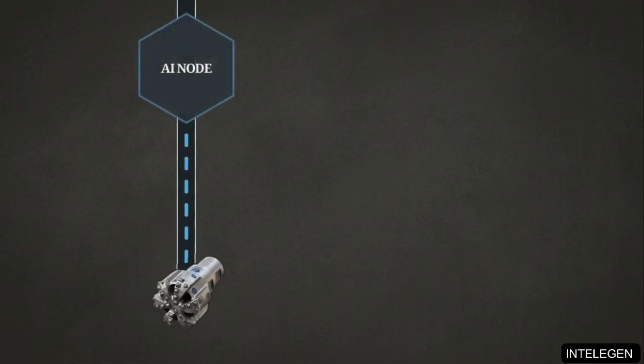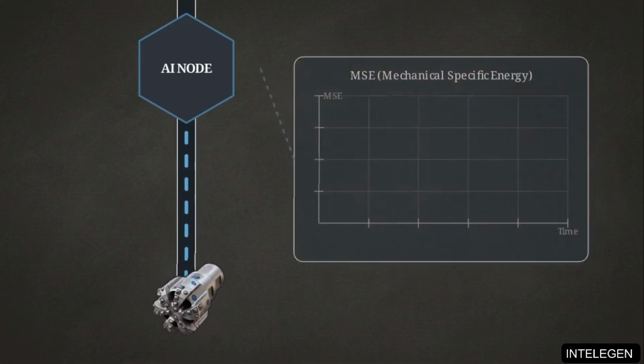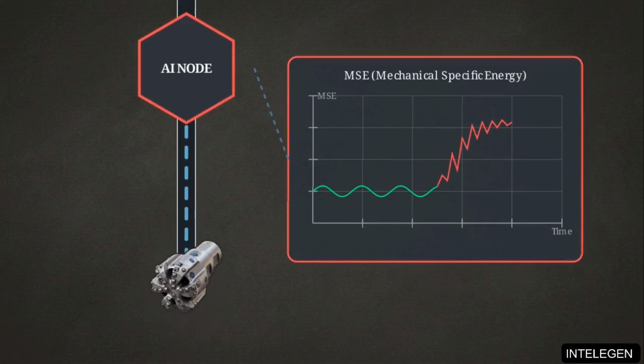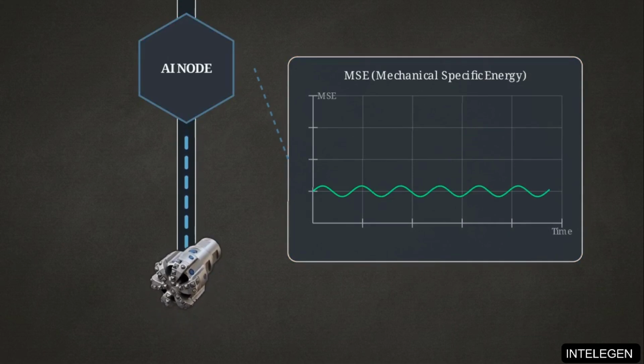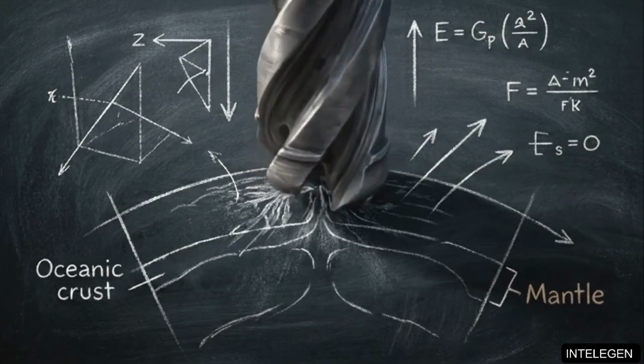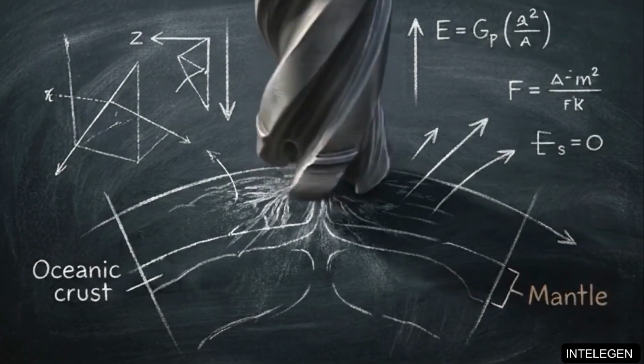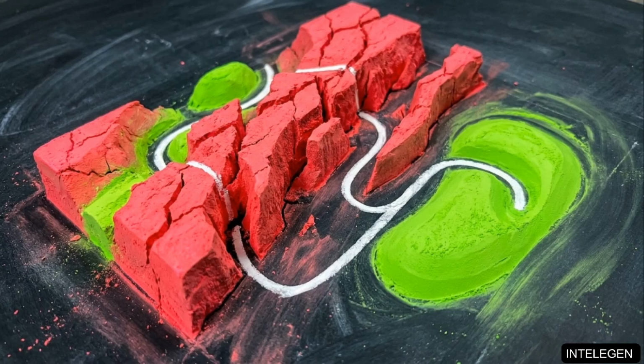Modern rigs use a closed-loop architecture. The WITS-ML protocol ingests drill string data directly into a central AI node. This agent instantly computes parameters like mechanical specific energy. If an anomaly is detected, it autonomously adjusts the bit's weight and rotary speed to prevent failure. This autonomous perception happens in fractions of a second, preventing the drill string from twisting off or fluid shifts from triggering a blowout. Simultaneously, a geological steering agent uses real-time logging data to dynamically construct models of deep earth fault systems, navigating the bit trajectory through complex rock layers.